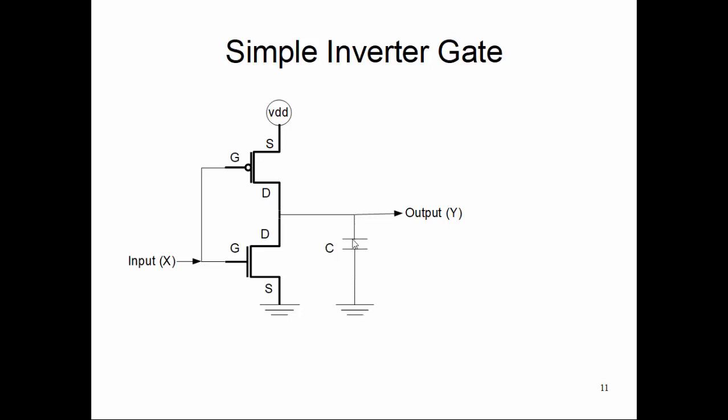A capacitance is a device which stores some charge. If some potential is applied between its two terminals, charge is stored, and if that potential is gone and there is a path to discharge, it will discharge that electrical charge and become empty. You can think of a capacitance as a storage tank: when electrical potential is applied, it starts filling up, and it stays full until you turn on a tap which can drain the charge, emptying it. If a connection to ground is established, the charges get away. That phenomenon is called discharging a capacitance, as long as it is connected to ground.